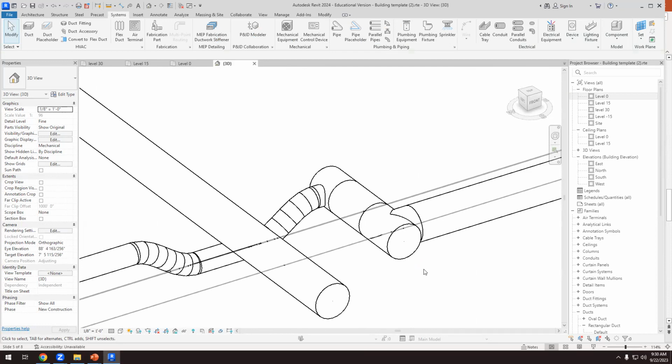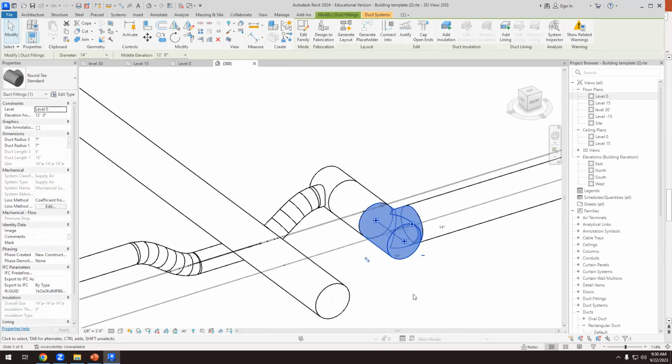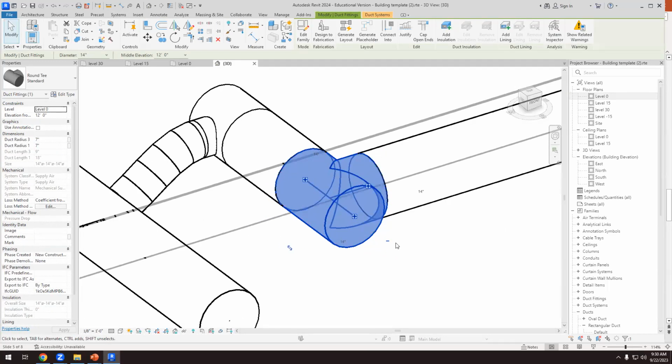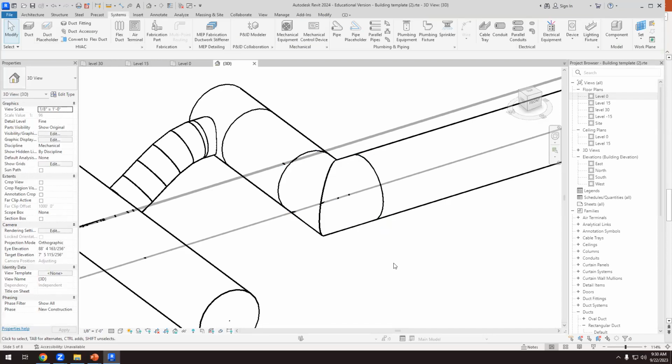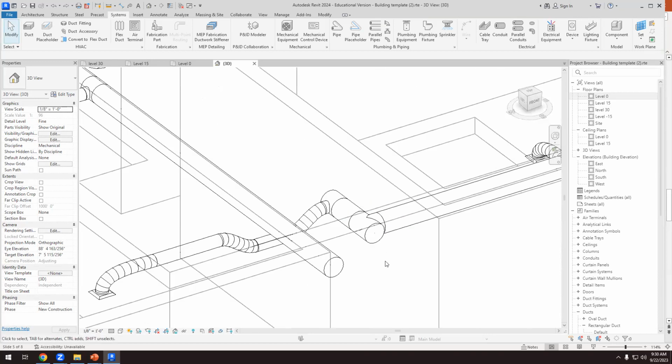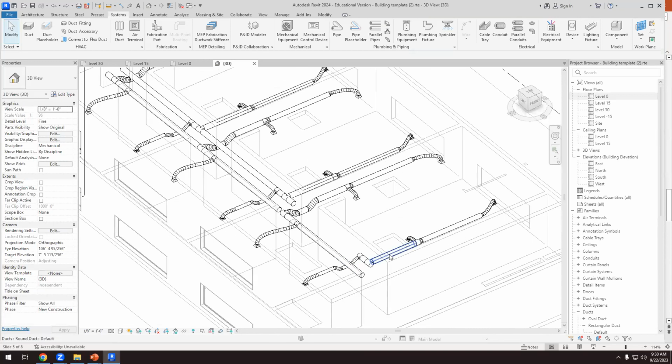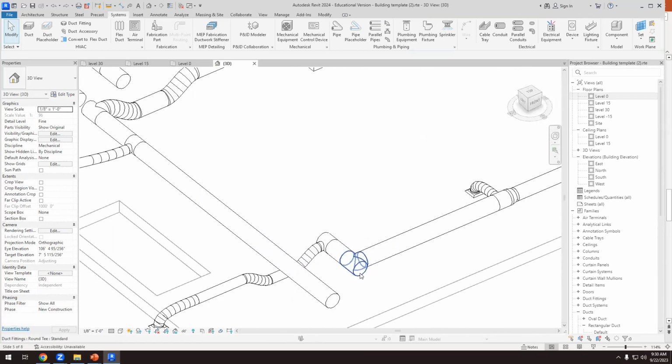That's another amazing feature. You see that I select a T. Okay, and here we have a minus sign. Click here. It becomes an elbow. Do it again. If you select a T, but that's the last branch that I have, so this can't be a T because we are losing air.